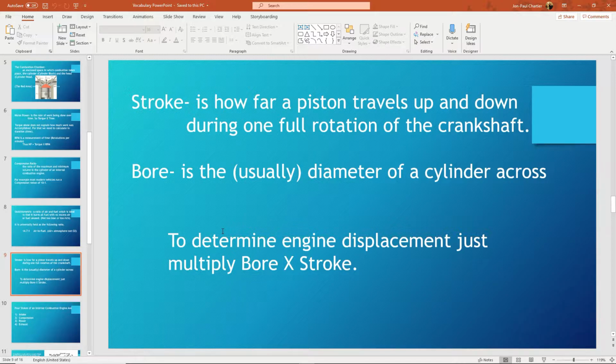So if you think about the piston going up and down and up and down, that's kind of what we're working with. Generally speaking, if we have a long stroke, we do not rev very high. Again, all the 18 wheelers, they don't rev very high. The Cummins engines don't rev very high. The Supra never revs very high. All those Nissans and the BMWs don't rev very high. However, that's the trade-off for big torque.